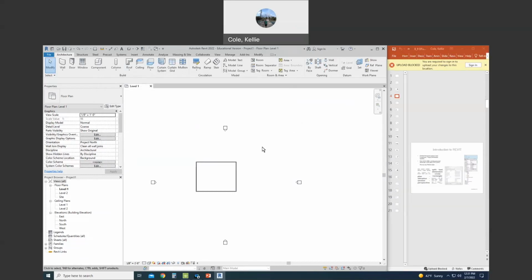And we're going to draw a few more things. I like looking in 3D all the time when I'm drawing in Revit because then I can understand visually the height of the wall I'm drawing. If you ever want to find a 3D view, you can find it in the top of the ribbon. So I'm going to refer to the commands in Revit. If I'm saying ribbon, it means look at the top. There's tabs at the top and buttons at the top. And then I'll also refer to the properties and the project browser, those panels on your left.